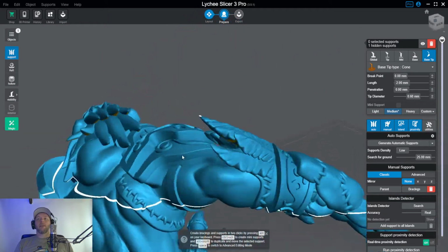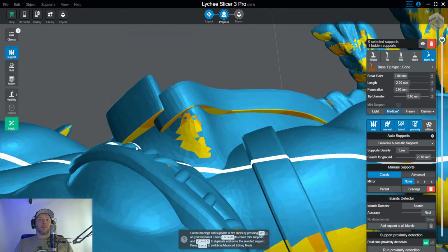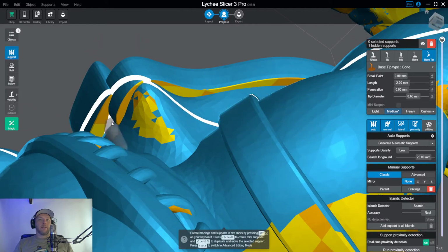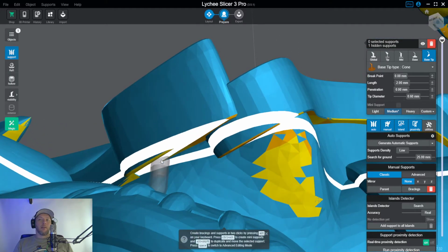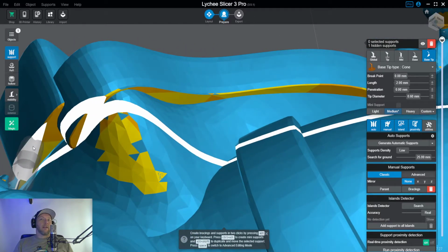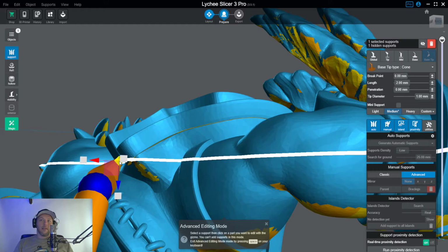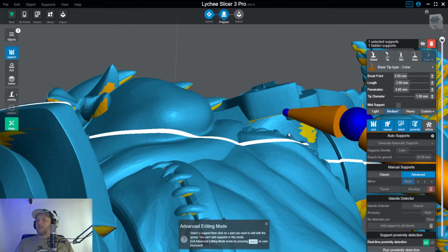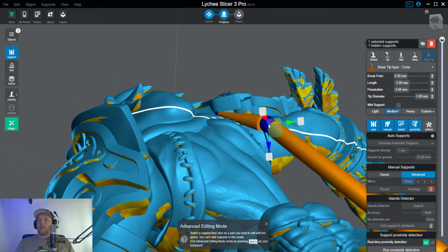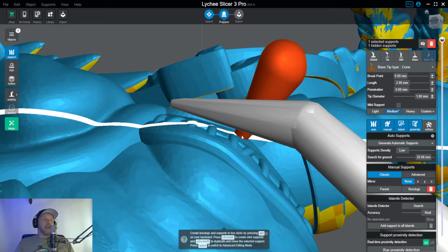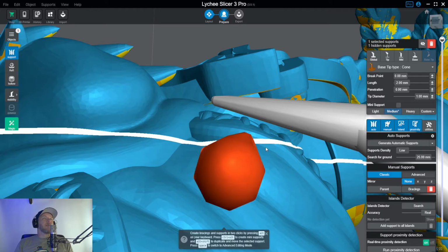Conversely, we're going to talk about mini supports and when to use them. Here's a prime example of a place you might choose to use a mini support. See right here, this island? I might be able to reach that island with another one, but what about the one behind it? There's just no way I'm getting a support in there from the outside. It's going to be too steep, and in order for me to get it in there, I have to shallow up the angle, and then it's too flat. This is just not really feasible in any sort of meaningful way.